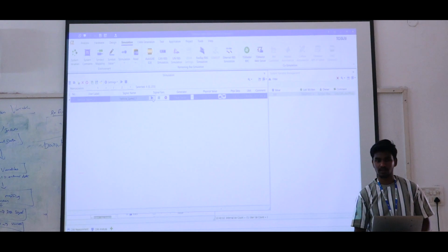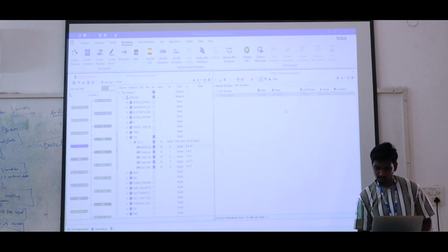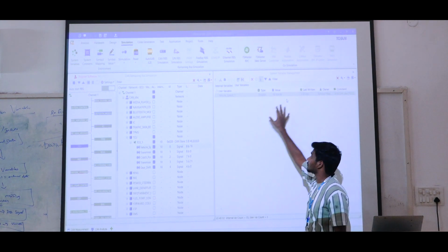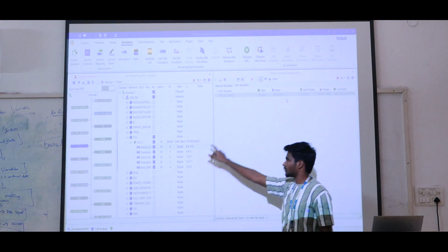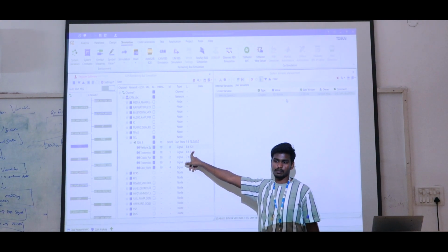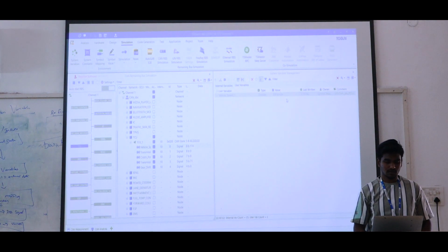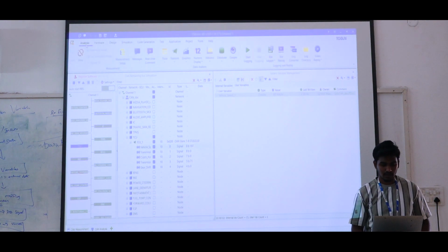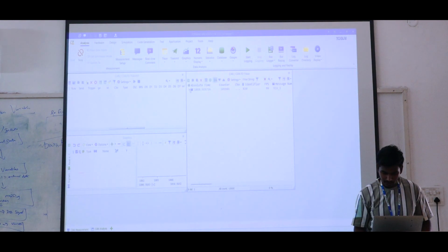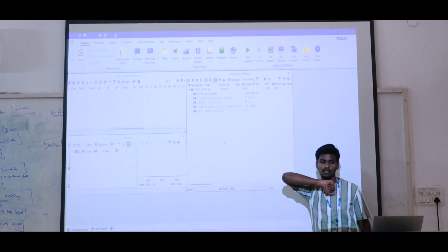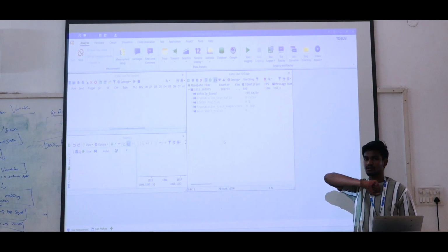So now you have to start the signal generation. Now you started now. So it is showing the output in our system variable. So now it is mapped to signal now. So now the variable generate the value and then we can see in our vehicle speed RBS also. Got it? So now we can see the same in trace window also. Go to trace. So now it is showing the vehicle speed is running data. Correct? What the point?